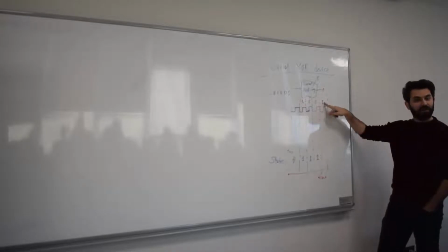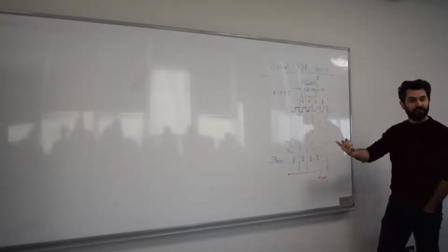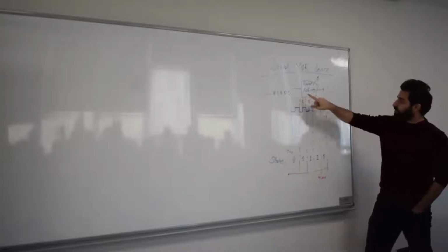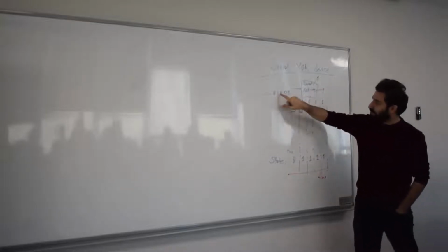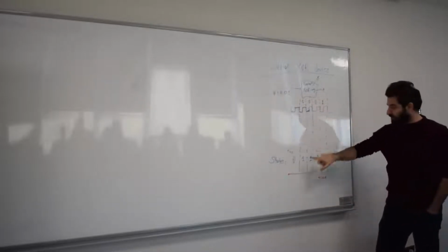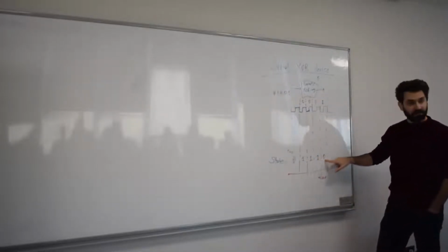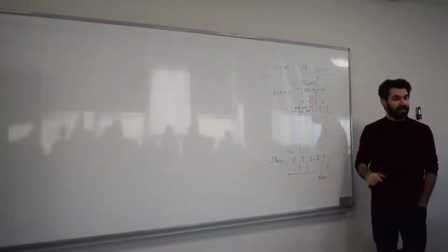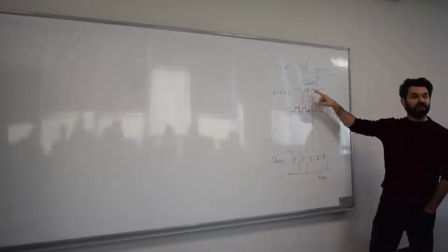If you XOR them, you get 0. That's your next state as well as your output. So this is your output actually. What goes in here is 1 0 0 1 0, and the corresponding bit positions in the output are 0 1 1 1 0, etc. That is the serial XORing device, and I want you to design this using a T flip-flop.